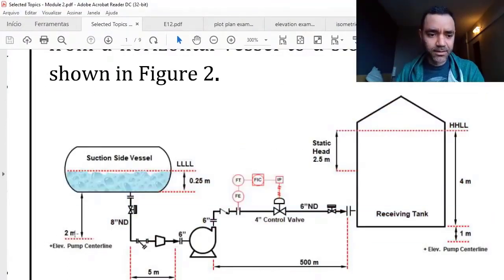In the schematic, the valve is shown in the vertical line. Not necessarily is it installed in the vertical line, because it is a schematic. What will tell you if this valve is vertical or horizontal is the isometrics, the more reliable document to verify the arrangement of the system, after going to the field and verifying with your own eyes.